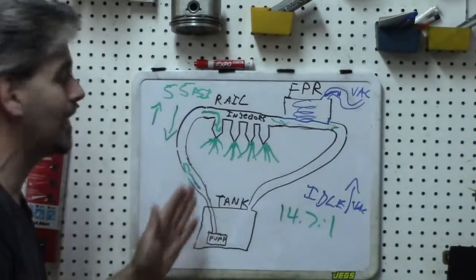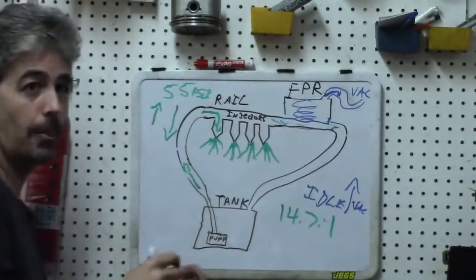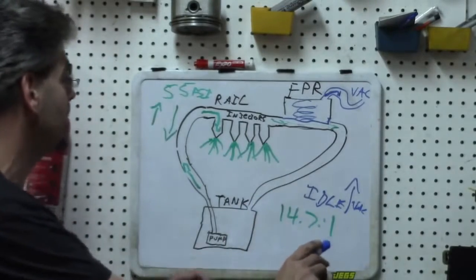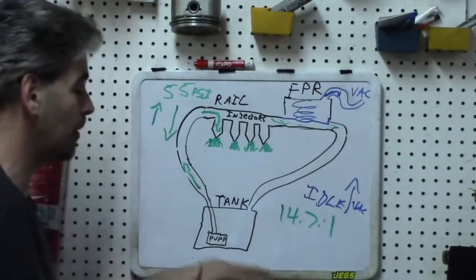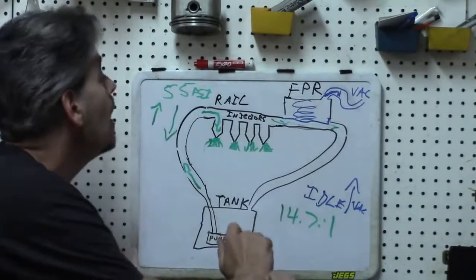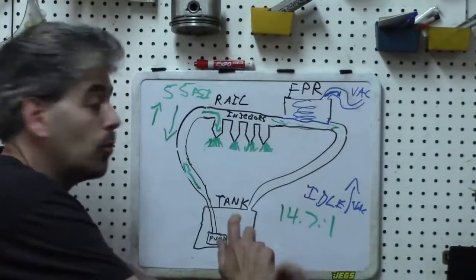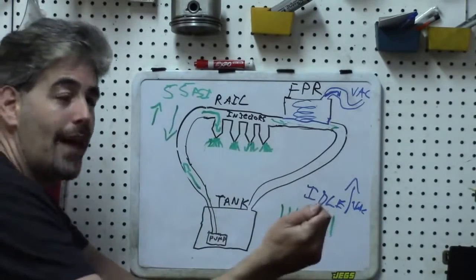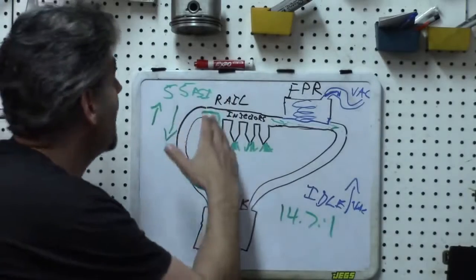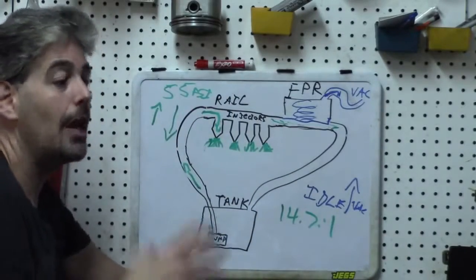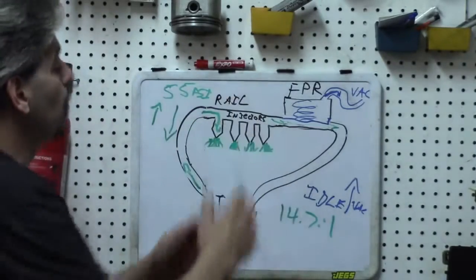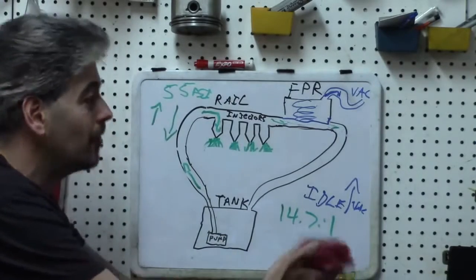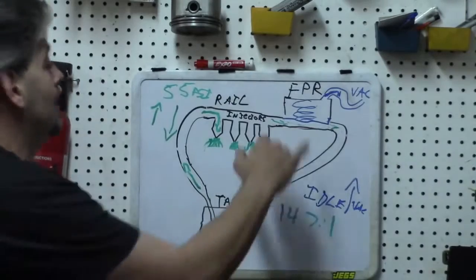So if you only see one line to your fuel rail, this isn't going to apply nearly as much, and the diagnosis is actually a lot more difficult if you have an issue. Now, let's get back to the original question from the start of the video. One of the things they often have you do when you diagnose a pressure regulator is remove the vacuum hose and look at the effect that would have on fuel pressure at idle. So go ahead and answer that question without having to look it up in a flow chart or anything like that. Just use your brain.